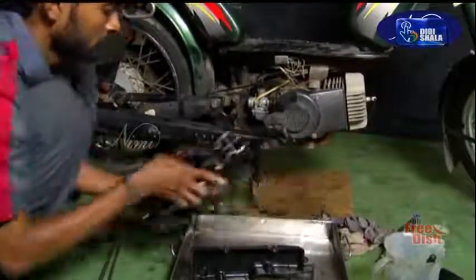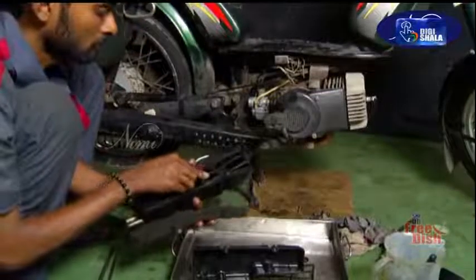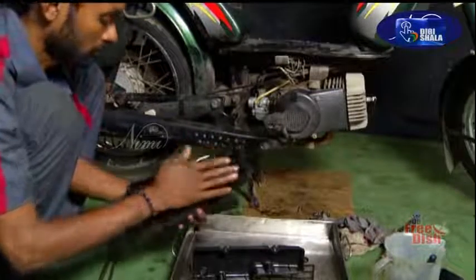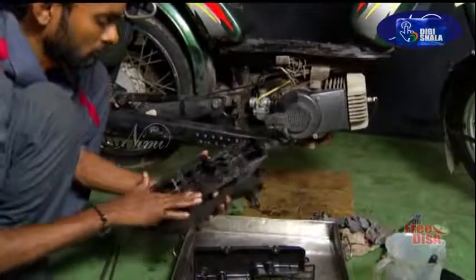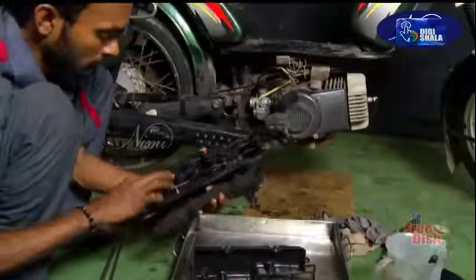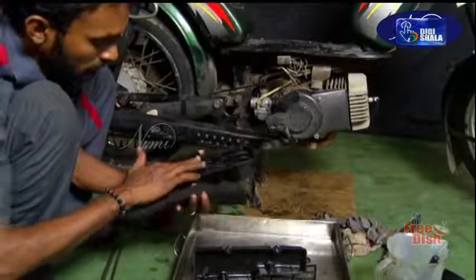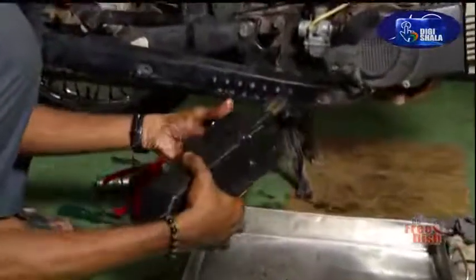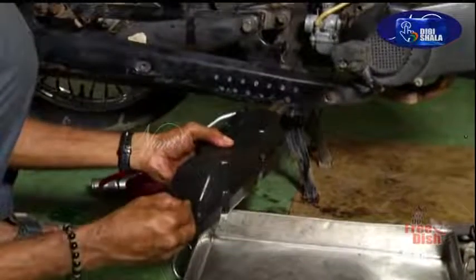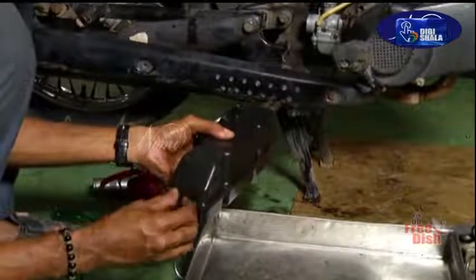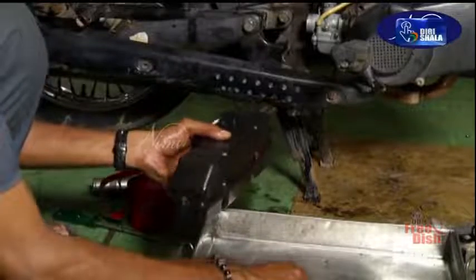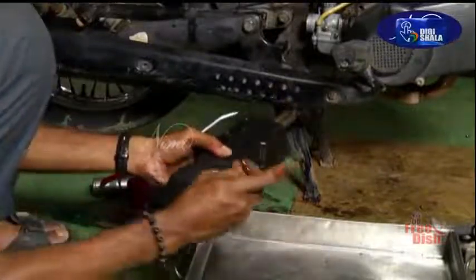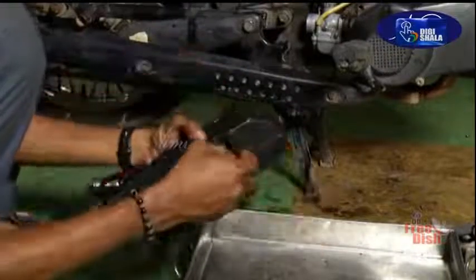Replace the air filter element if the recommended replace interval is reached. Refer to service manual for details. Attach the filter unit to the assembly. Secure the air filter screws tightly by means of a screwdriver.